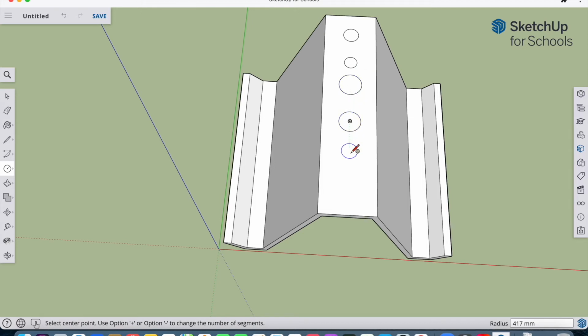I would like you to evenly space these out, as neat as you can make them, the same size. The way you're going to make them the same size is by using your dimension tool on the bottom right hand corner of your drawing. You're going to go back to here, go round, then on the bottom right hand here, see how it says radius? Let's make it 300. And then 300. And it starts to automatically find the exact same size, 300.